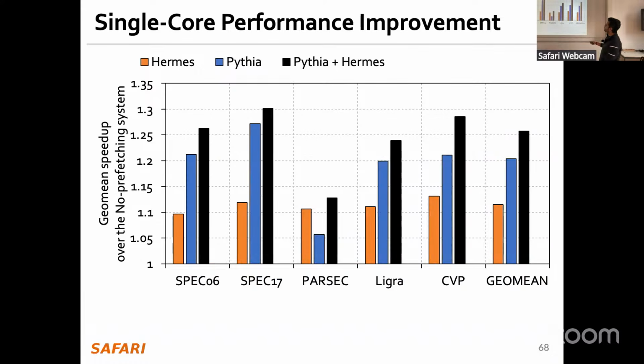The other thing is that if you add both of these mechanisms on top of each other, so you not only have off-chip prediction but also prefetching, that additionally provides a performance benefit. I'm just going to foreshadow a bit. This is the average case behavior. That does not mean that every workload is getting additive benefits. In many workloads, and that's what the third work is, I'm going to give a brief overview, you would see that these two mechanisms actually destructively interfere. One kills the other one's benefit. If you let them run individually, they are really good.